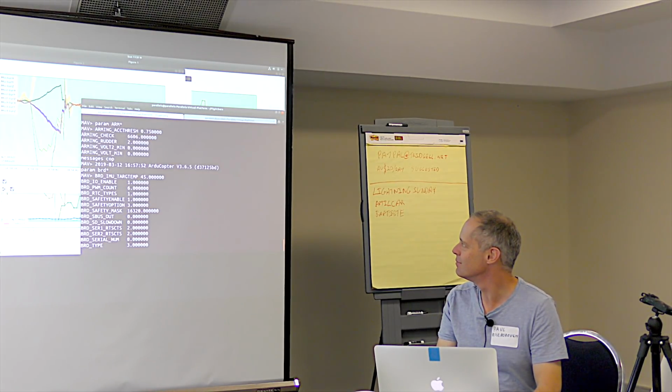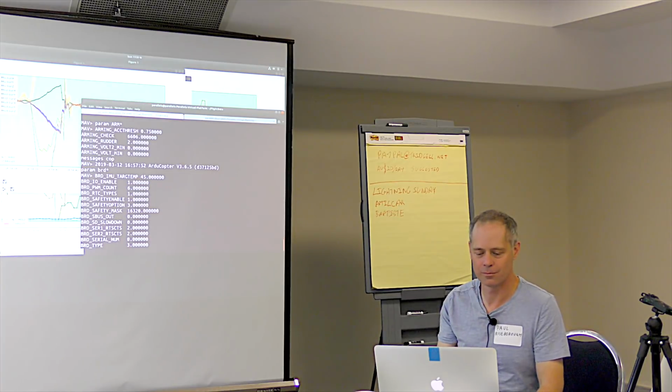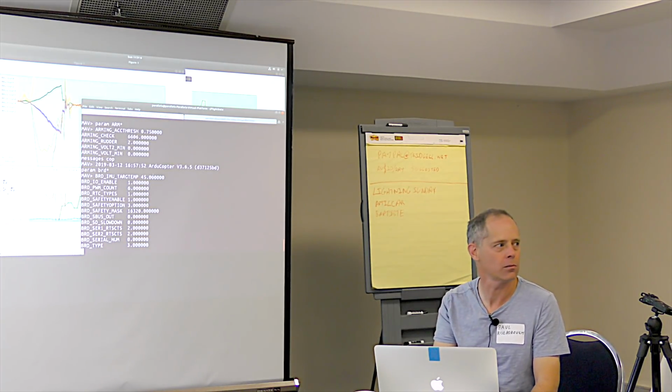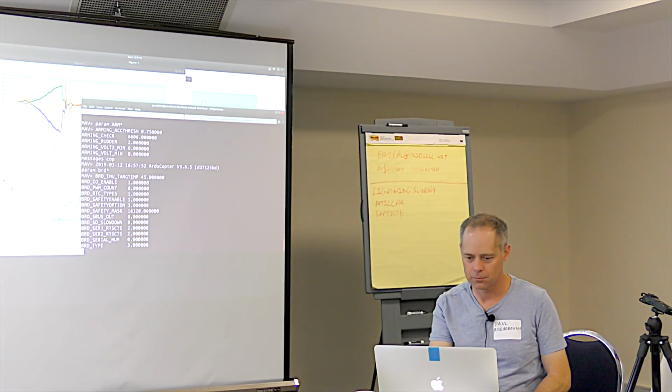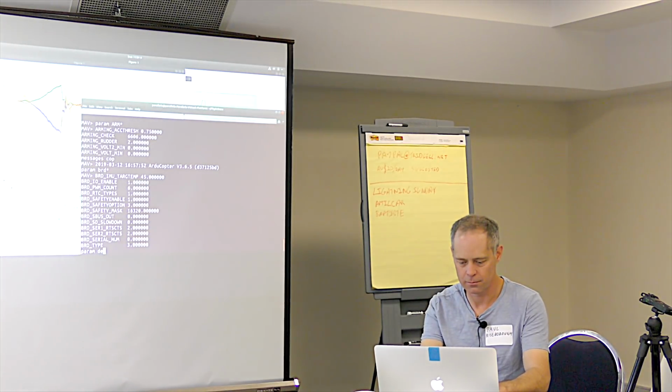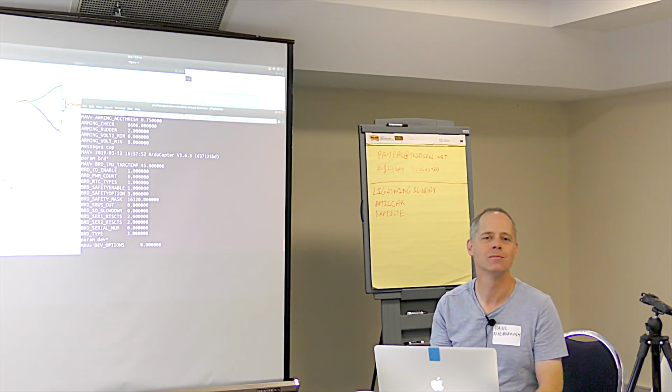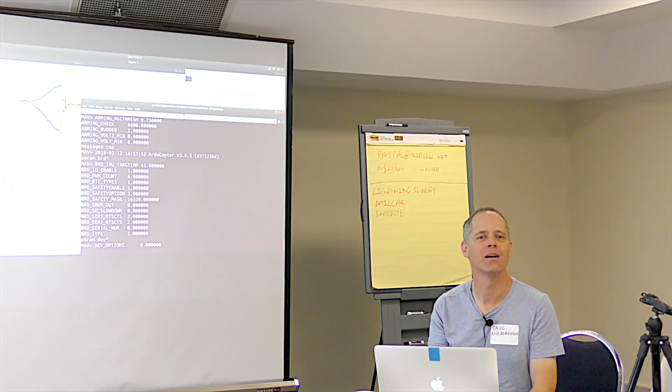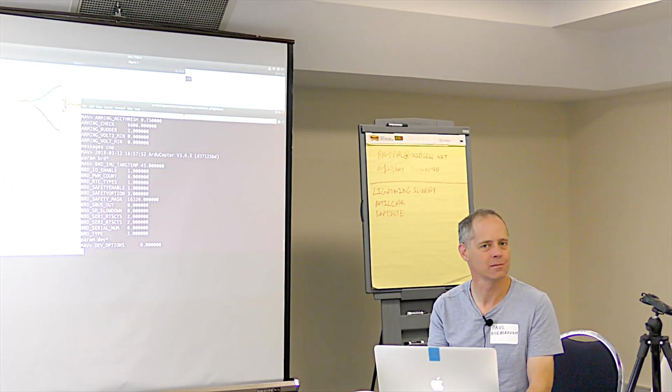We sometimes get problems with the board type being wrong. Oh, we get that all the time, especially when they copy an old parameter batch. Well, the dev ID is that 1 to a pixel. So you should be able to get the actual board type. You know what this board is? This was, I believe, a very old CUAV board. Oh, was it a Pixhack? It's a Pixhack V3, I think. And the user reported that they had a batch of them, 3 of them or something, that had this problem. I've got one of those boards, and you tested yours and it was fine. So it might have been an early prototype that had a different configuration. Yes, exactly.